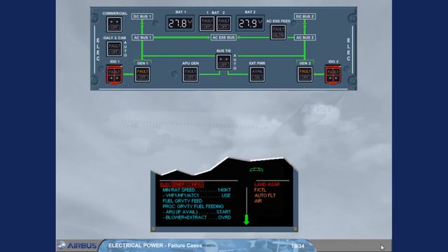Then below flight level 250, you may start the APU only if it is available. Note: when the APU master switch push button is set to on, the batteries are connected to the DC BAT bus for a maximum of 3 minutes. As the next step concerns another system, we will stop here and study the indications on the right side of the engine warning display.